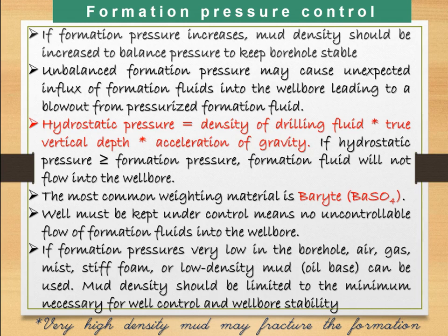The most common weighting material which can enhance the density is barite, often BaSO4, barium sulfate, and the well must be kept under control, meaning no uncontrollable flow of formation fluid into the wellbore. So regulation is important. Neither should it be very high, that formation fluid pressure, nor very low. That means my drilling fluid pressure must be regulated properly.